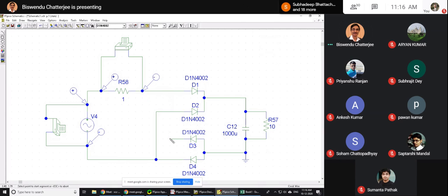Now, you just click once here, the start point will be defined. Now without clicking, drag it and click again here. It will be joined like this. Now you press the escape button, the pencil will go and change to the common cursor. If you click the cursor anywhere on the right, it will be changed to green. So in this way, bus lines are drawn and parts are placed.